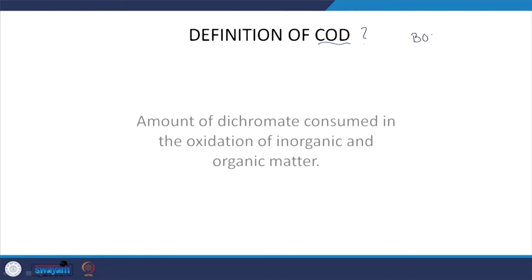The BOD test is typically 5 days at 20 degrees centigrade temperature or 3 days at 27 degrees centigrade, but typically people go for this test, okay. And also it is not easily reproducible. The reproducibility of this particular test is pretty low, depending upon who is conducting the test, and more importantly the kind of waste. Why?